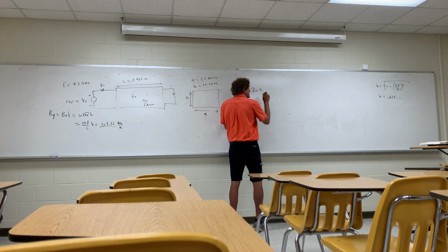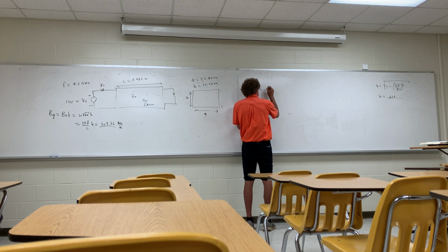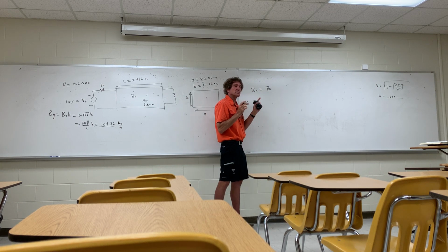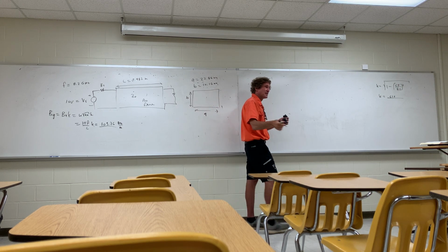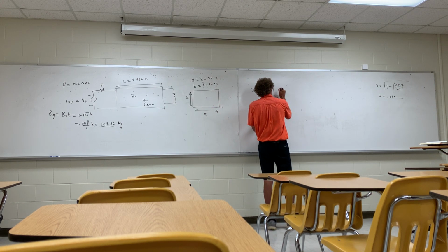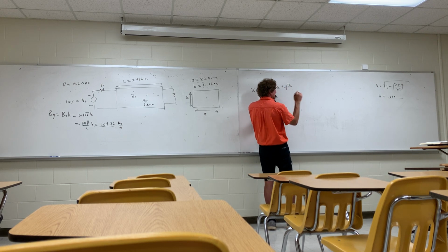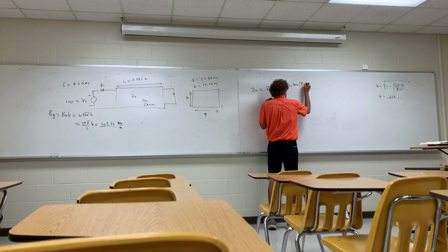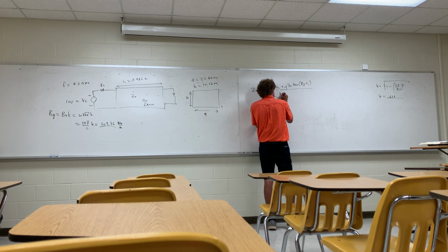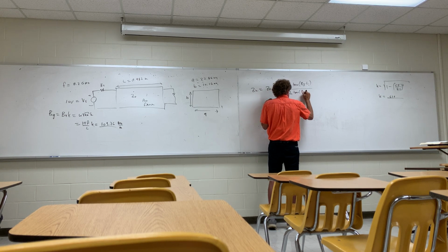All right, now we go to this. Zn. You have to get the input, the characteristic, or the input impedance. So the first thing you have to do is, and I'll give you this calculation on the quiz. Hint, you don't have to memorize this one, but if you use it enough, you don't need to worry about it. Times ZL, right? Plus J Z naught, and that's Z naught for the TE mode, 1 mode, times the tangent, and you have to be sure this is beta in the guide times L, over Z naught plus J ZL tangent of beta in the guide times L.